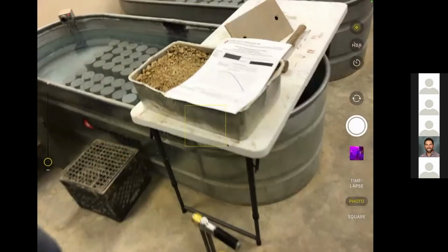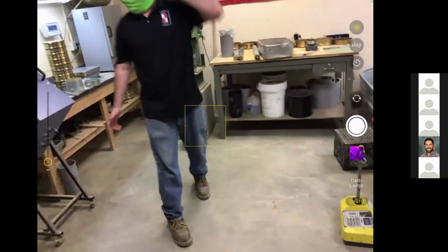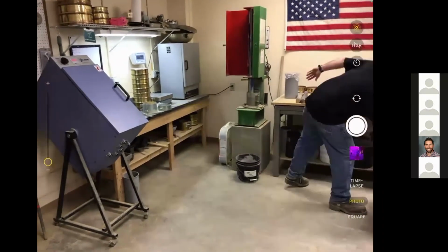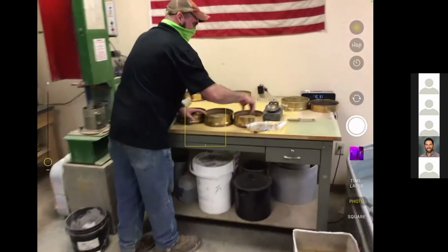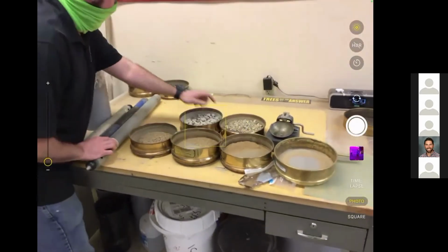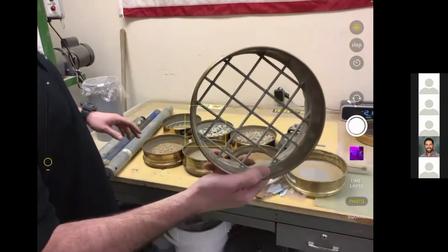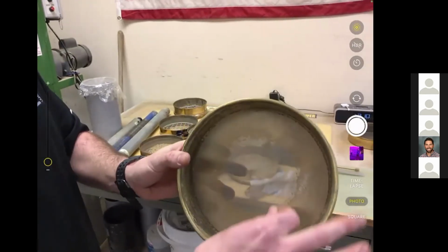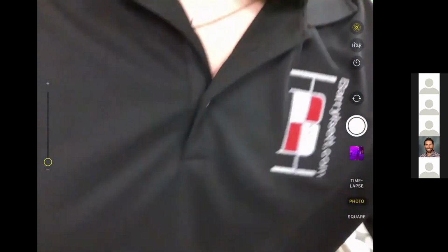The other thing we do as far as lab work is a soil class. And for the most part, we take sieve nests and take a known set of samples. We will sieve it through a known set of sieves. And these sieves go from 1.5 inches all the way down to a 200 micron sieve. Okay, and that'll produce a gradation.